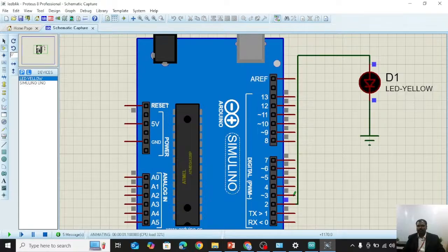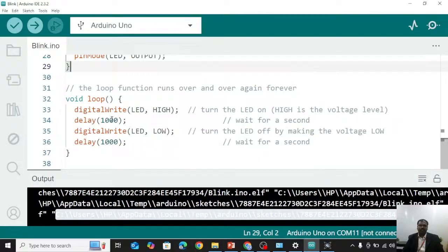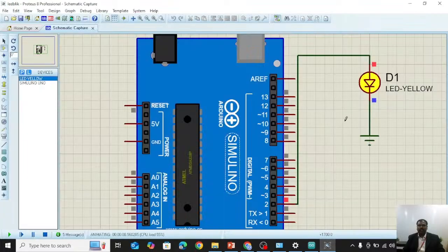It is just a simple connection. You can easily drag and connect it, so it is so easy. Once you start, the LED starts blinking. If you don't program it and connect it to this Arduino, it cannot work properly. It blinks because we are using a delay function here, 1000. If you use 100 as the delay, it will blink quickly. This is a major thing.